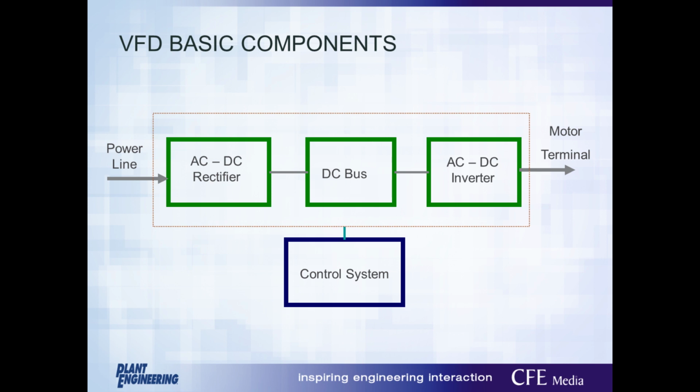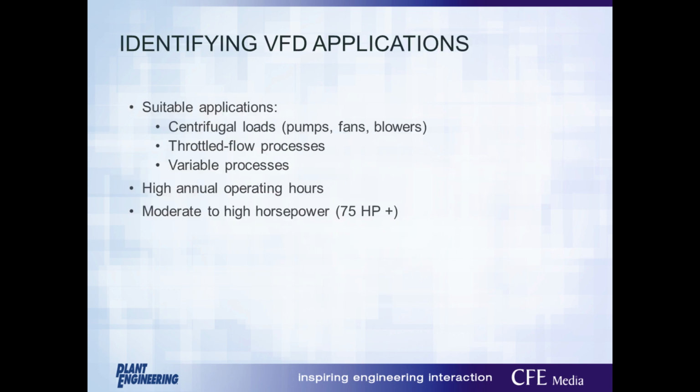So when you walk into a facility, you may hear some high-pitched audible noise if VFDs are being used. This is called the switching frequency or carrier frequency, and is in the kilohertz range, maybe 2 to 20 kilohertz for standard commercially available VFDs in industrial applications. Of course, not all VFDs are designed like this diagram, but just the simpler ones.